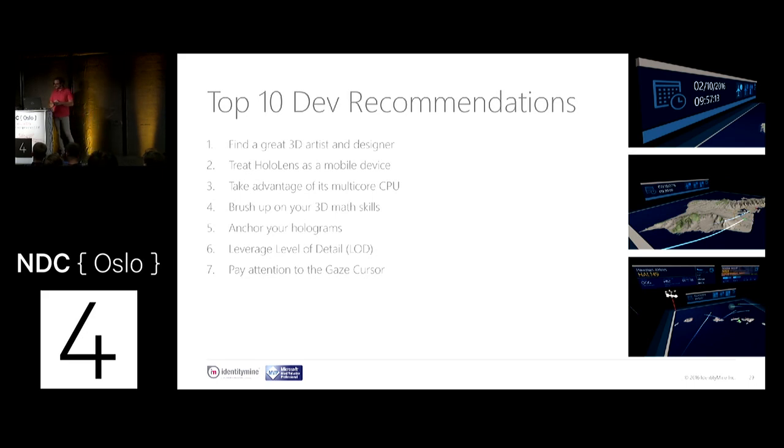And what most apps do, and also the HoloLens start menu, they show an open ring gaze cursor when the hand is in view to tell the user, okay, you can now interact. And they show a flat circle, something like this, when the hand is not in view, right? To give the user the information: open cursor, you can interact. The other cursor, nope. Those details really matter. They make a good experience, and you probably want to have a good experience. So pay attention to those details.